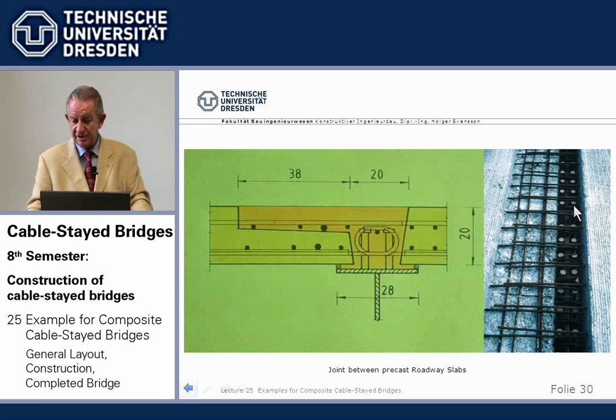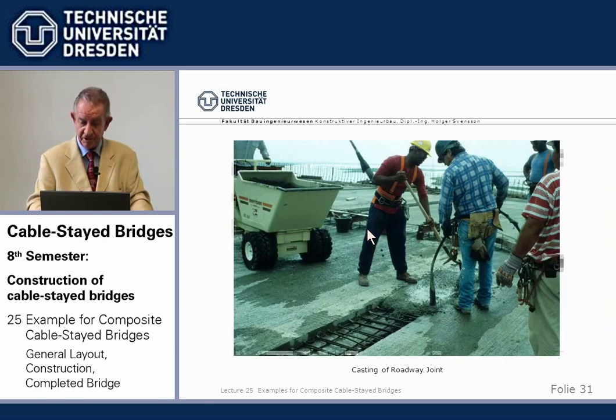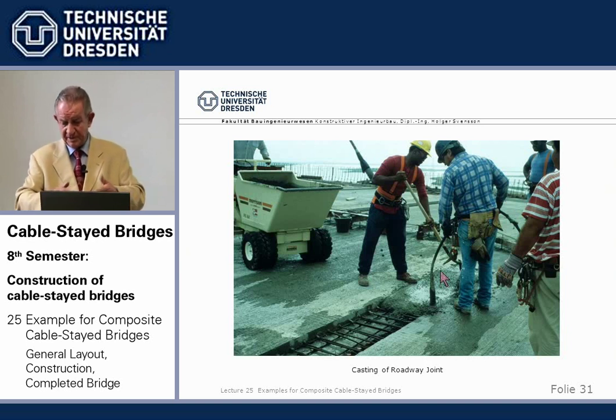We see here the joint, the straight lap splices on top. We see here the shear studs protruding from the top flange of the cross girder, and then it's cast with special mixed concrete, small aggregate, 0 to 16, super plasticizer, low shrink, and so we did not have crack problems in these joints.